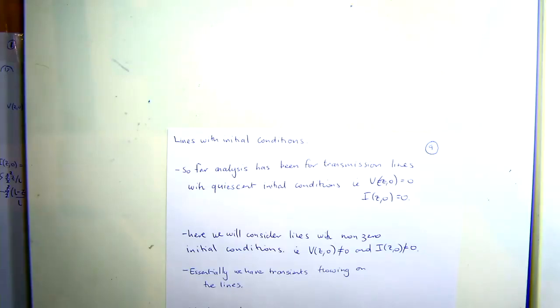And if you've got a very sharp pulse, you can work out what the frequency components are. So you've generated a huge pulse, lots of energy across this antenna, and it's radiated everywhere. That was part of the reason you use these kinds of things to build these structures, because trying to switch 200 amps in 10 picoseconds is bloody hard, right? No matter what IGFETs or IGBTs you try to use, you can't do it.